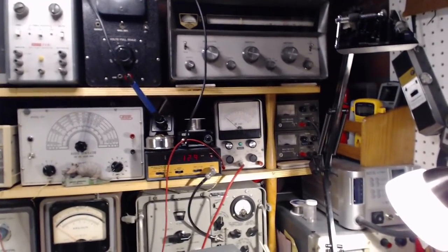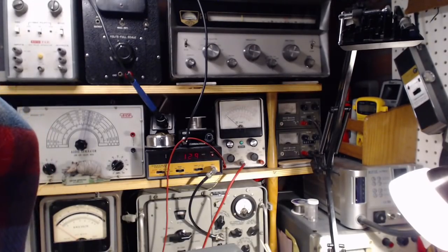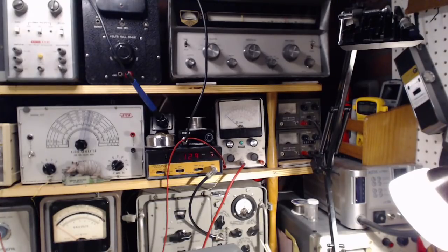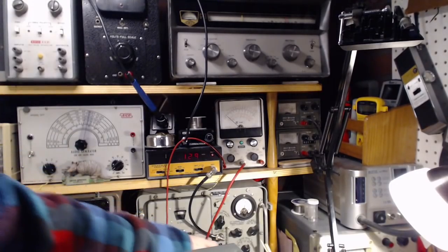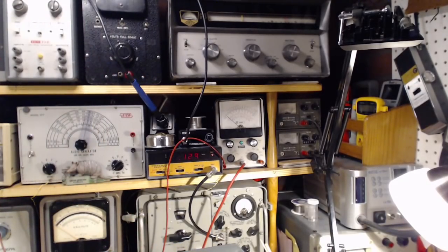Now while we do this, we certainly want to be listening to the radio, which we are. And what are we listening to going in? Nothing. So let's just clip this way at the front end here. I'm going to put it way up here. Grid of the very first tube. Grid of this tube. Fairly heavy signal. Let me knock it down. 1,000 hertz.